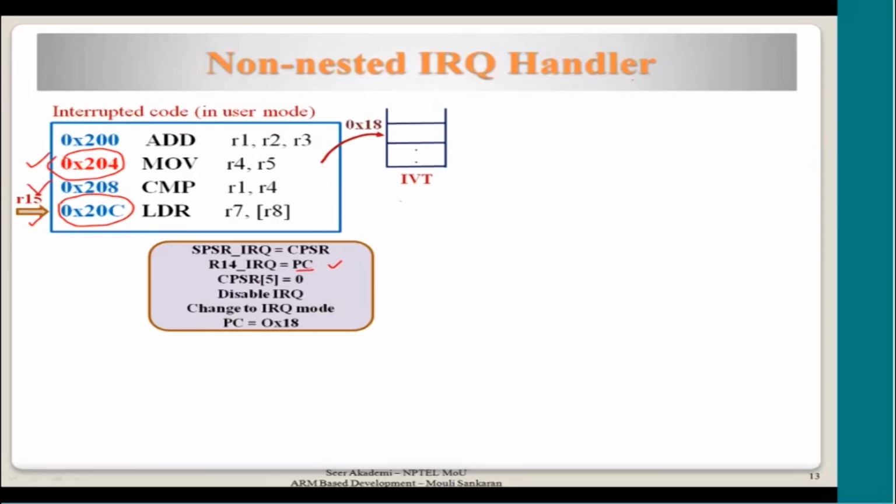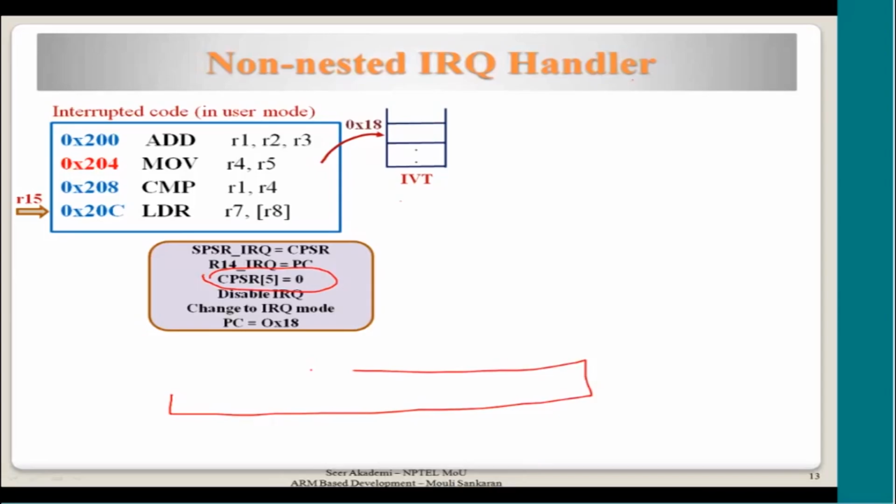And then, can you see the reason why this bit is there? This particular thing is there. Think it over. This corresponds to CPSR bit 5. Okay, CPSR. If you want to, this is CPSR. Okay, 5 bits. Initial 5 bits are what? Mode, right? Mode bit. Which mode? System mode, user mode, abort mode, whatever.